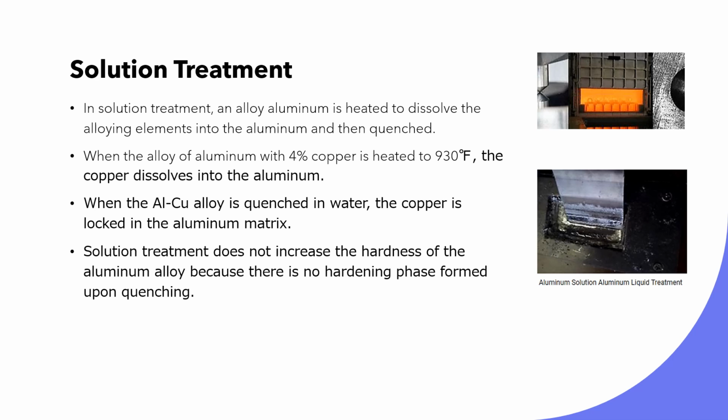So we're gonna use aluminum alloy and we're gonna heat treat, and this heat is gonna dissolve the alloy elements back into the aluminum. And then we're gonna quench, remember, like another heat treatment. Even though it sounds so watery, both of them are heat treatments.